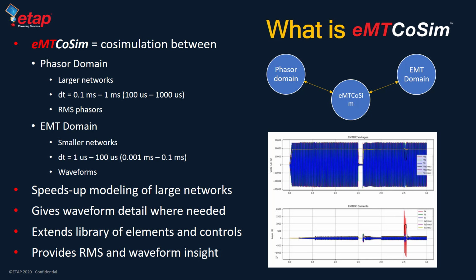If you take this chart, for example, the same chart now shows instantaneous waveforms for voltage and current, but we also show RMS phasors produced from a phasor engine. This is not the same as calculating the phasors from the instantaneous data using one engine.